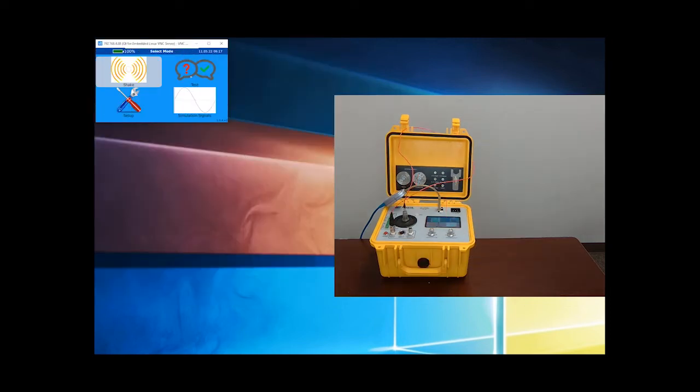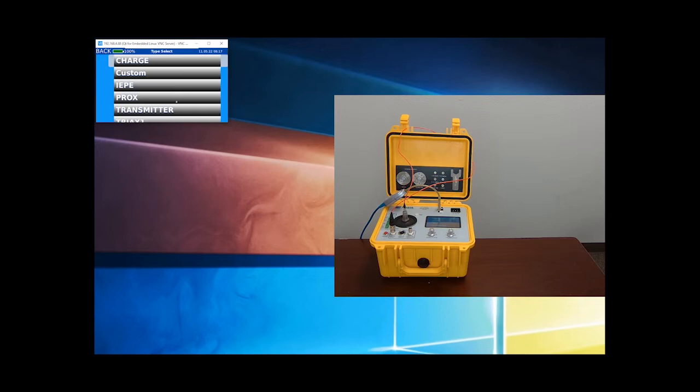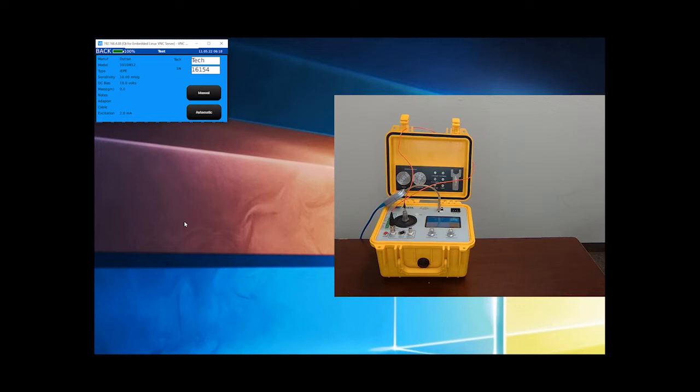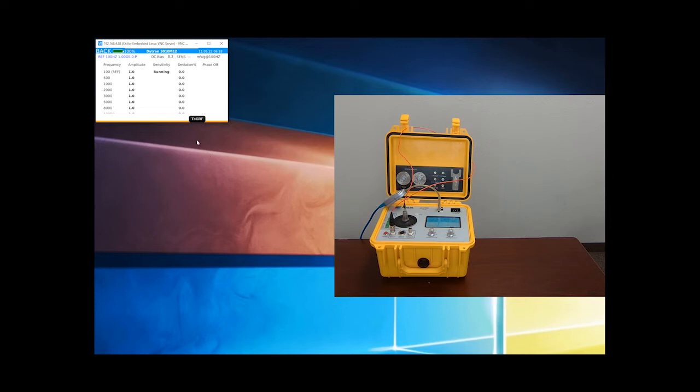Back to the automatic test. We'll run the automatic test for an IEPE by Dytran. This is the 3010 M112. And then I'll click automatic. And you can see now we've added a table view. And this is in addition to the graph. If you still want to see the graph, you would select on screen or press down the right frequency knob.